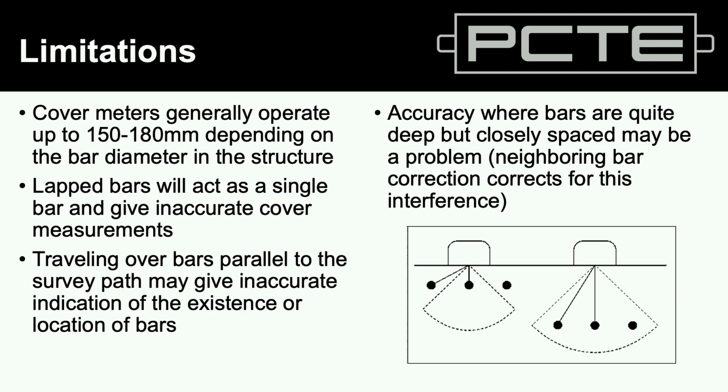Doesn't mean we can't use the cover meter for a quality check, but it does mean that we don't want to do it with default settings. We want to have a process and a sort of mock up or test it on the reinforcing before it's cast, or on an exposed bar, so we know we're getting the right measurements in the right contexts. Also, if you've got very congested, very unusual reinforcing layouts, or it's a structure you just know nothing about, maybe GPR has some role to play there, even though it's not as precise.